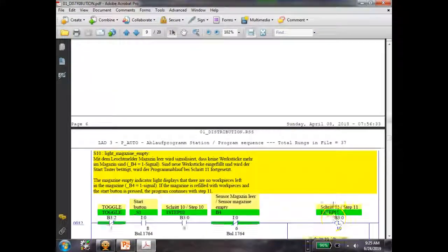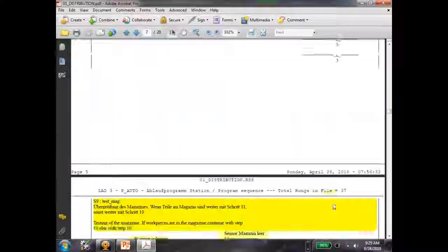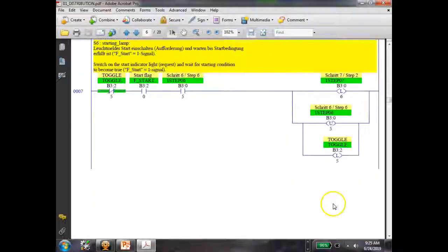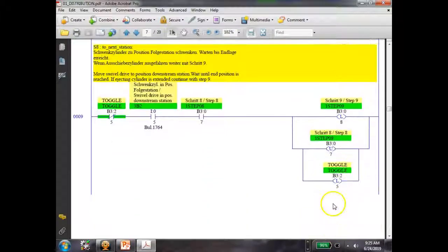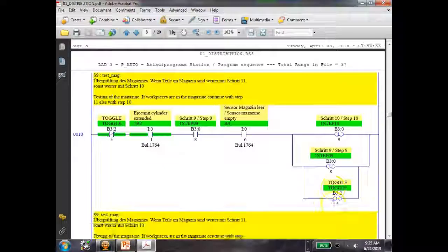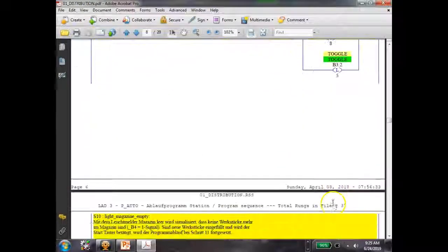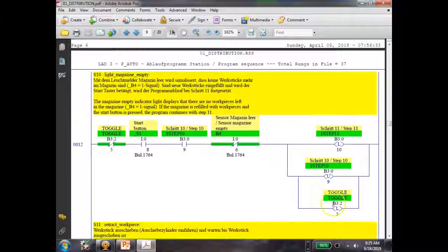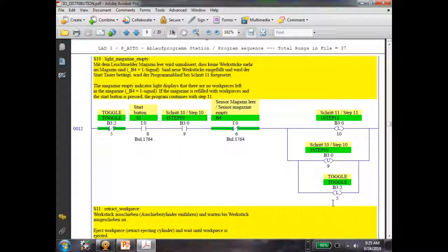So this is our lab that we're going to play around with these latch unlatch, and this is just a sequence, and they sequence through this to decide when they're going to actually turn inputs and outputs on. So this is very popular. It's kind of like a sealing circuit, but what's nice about this is your latch and your unlatch don't have to be together, right? You understand? It can be just about anywhere.